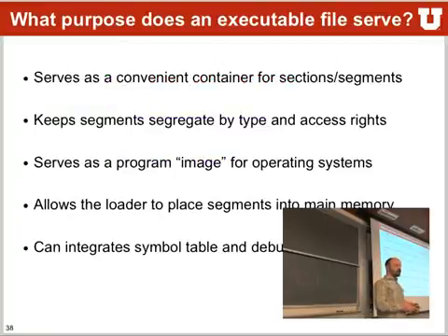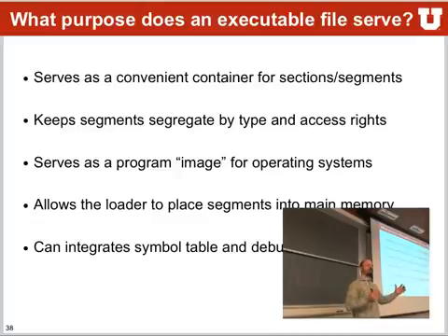So what's the purpose of this executable file? Well, it basically serves as a container before you really put it into applications that can program your microcontrollers. They keep different segments partitioned with different access rights. They serve as an image for operating systems. So if you have ever upgraded your Linux router, for example, or like your Wi-Fi routers, you usually get one of these images, and then you take this image and program it into your microcontrollers. They oftentimes have debugging information, so your IDE can actually find out what's written where and actually find the link back into your C code. That's all stored in this executable file.